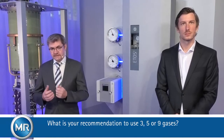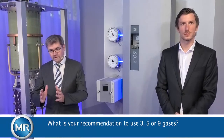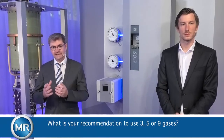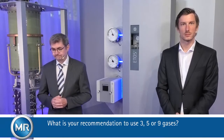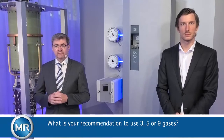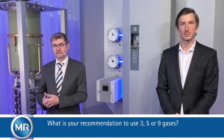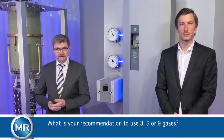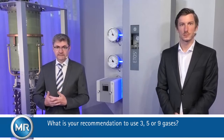When you use the DGA 5, for example, you can do a bit more of a diagnosis. You can decide between thermal and electrical faults directly with the results from this system. And with the DGA 9 system, you can do the full DGA interpretation according to the standards, the IEC and the IEEE standards, according to the Duval's triangle, according to the different gas ratios these standards provide.